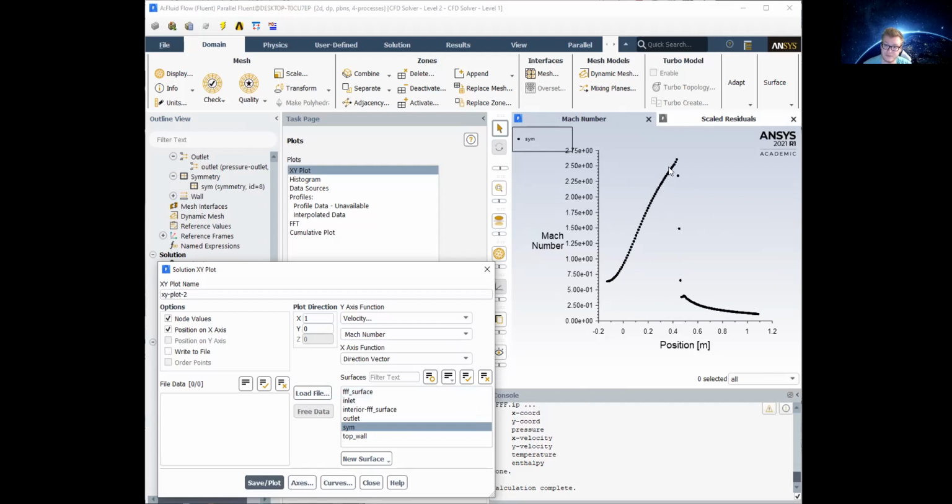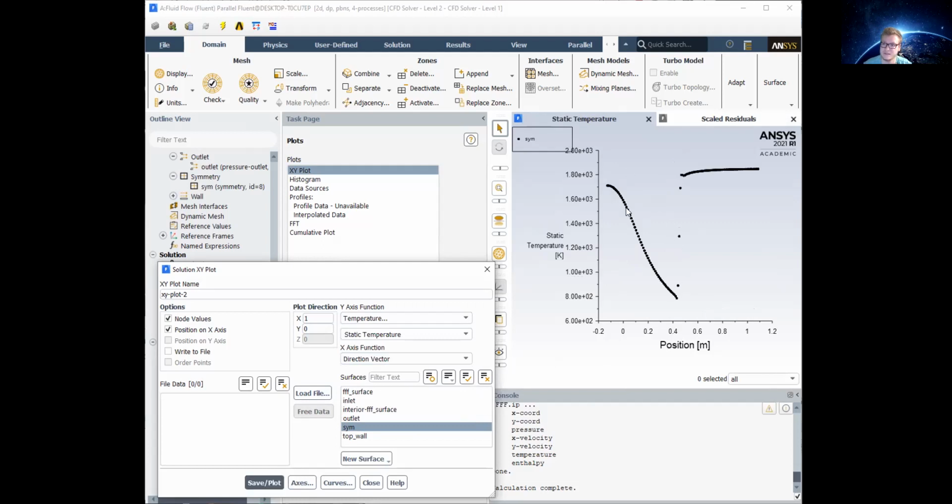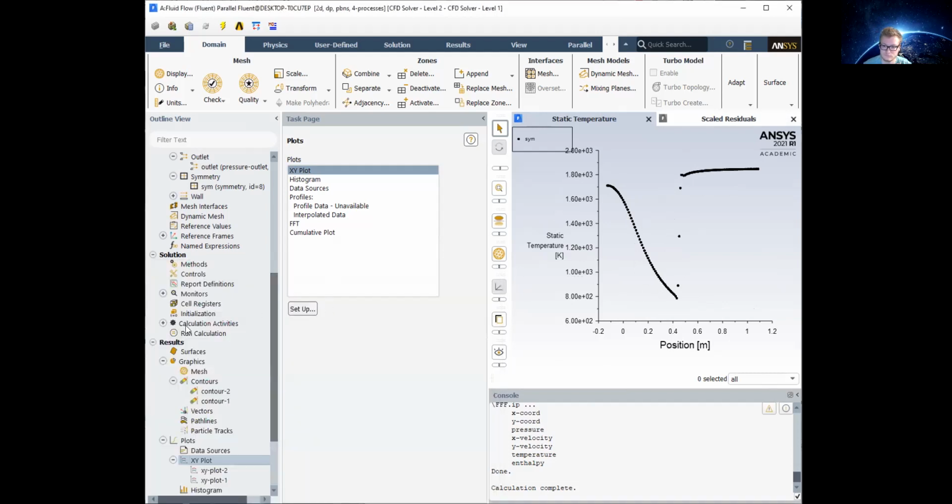As you can see, the Mach number is increasing as it goes through the rocket nozzle. But then once the shock wave happens, it acts as a diffuser and slows down the velocity. And we already did pressure. Anyways, let's do temperature real quick. As you see, there's a huge temperature drop as the pressure also drops. Then once the pressure goes back up, so does the temperature at the end here. It's more pressure, more temperature. And that'll be about it.